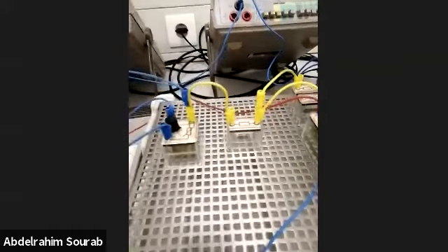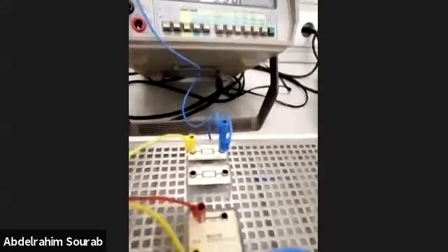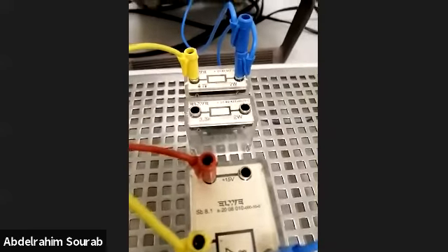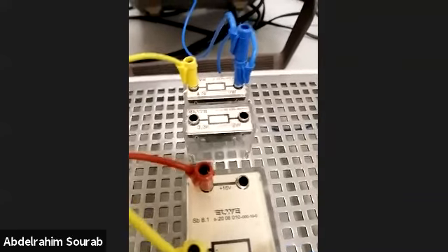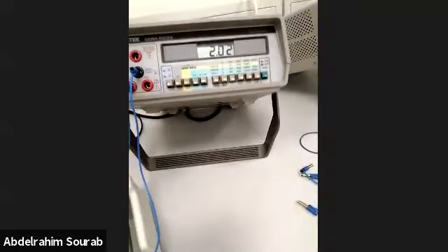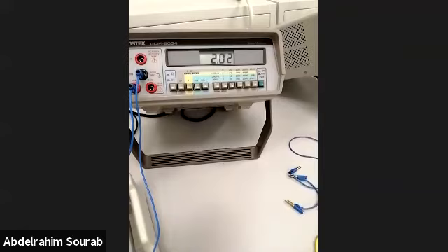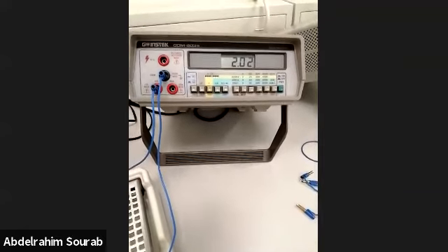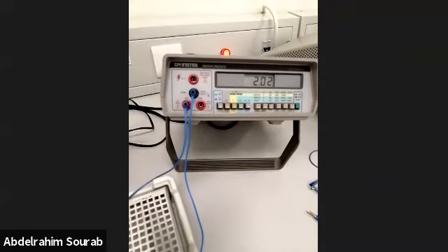Okay, so for this part, we have seen that while changing the load resistor, which is connected in the feedback, we got a variable output voltage while the current is stabilized at a value 2.02. Then we have a constant current source from this op amp.